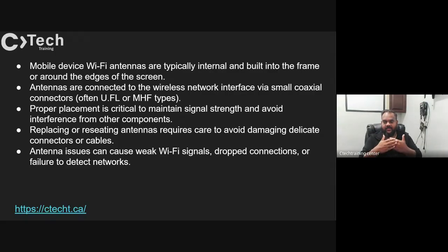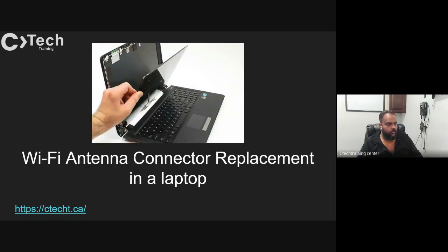The antenna itself, you'll see a small board, a logic board over here, and then you see this silver tape. This is actually part of the antenna as well. So you do have to be careful when you're removing this. You have to apply a lot of heat and alcohol to remove it and put it back properly with the proper glue. If you rip this too, it doesn't just stop working, but you'll get slightly less range.